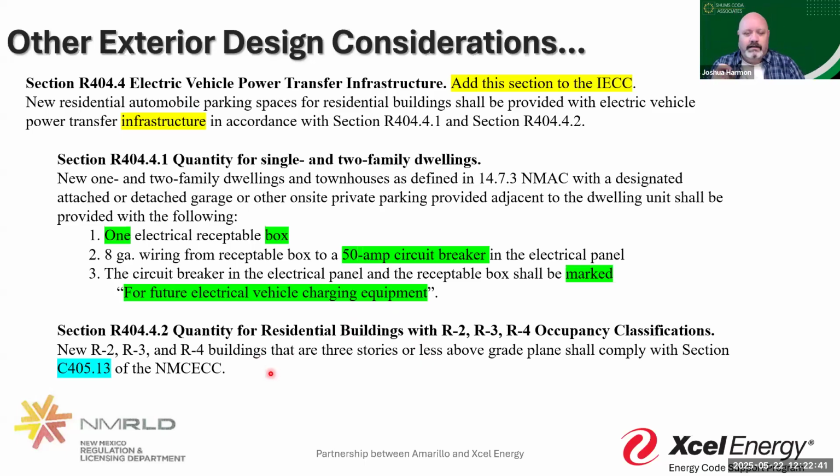New Mexico requires, as part of their energy code for residential, a single electrical receptacle in an attached or detached garage with a 50 amp breaker tied to it. That's for future EV charging equipment. It doesn't say you have to put in a charger. It just says you have to put in a conduit, a cable, a breaker, and a box.